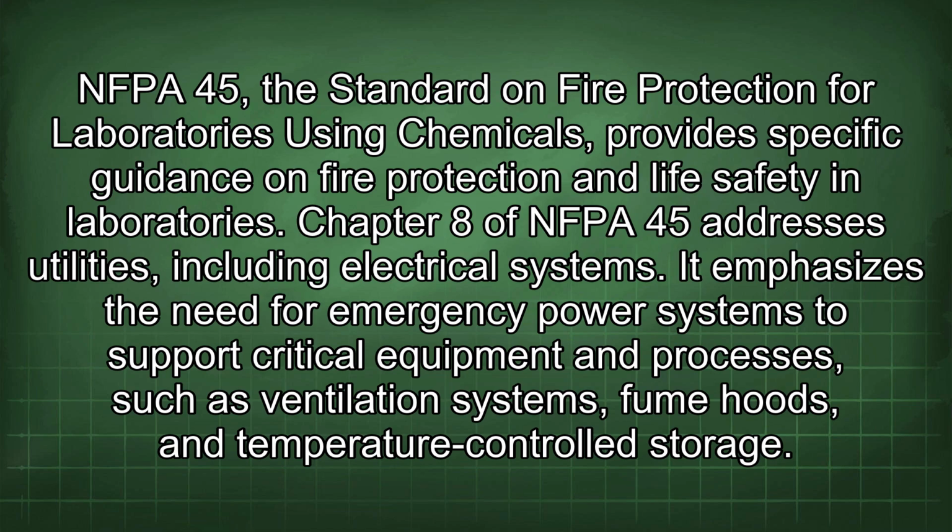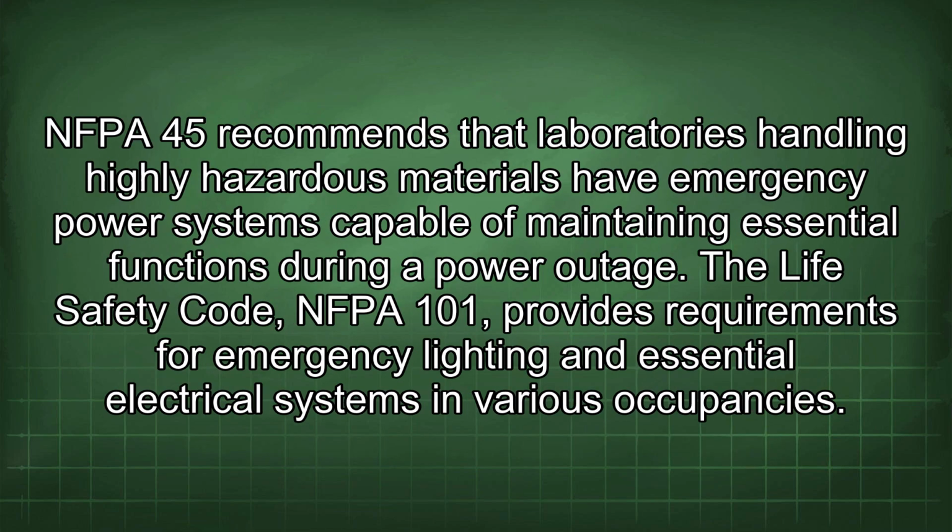NFPA 45, the Standard on Fire Protection for Laboratories Using Chemicals, provides specific guidance on fire protection and life safety in laboratories. Chapter 8 of NFPA 45 addresses utilities, including electrical systems. It emphasizes the need for emergency power systems to support critical equipment and processes, such as ventilation systems, fume hoods, and temperature-controlled storage. NFPA 45 recommends that laboratories handling highly hazardous materials have emergency power systems capable of maintaining essential functions during a power outage.